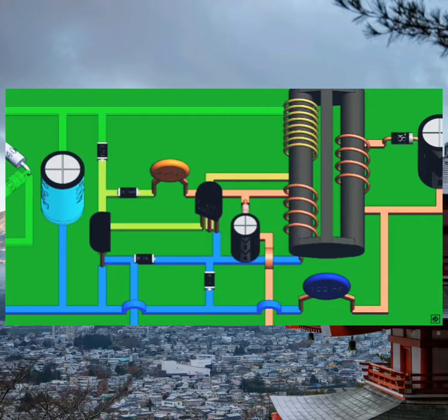Now, this current passes through the 2 megaohm resistor to the base of T1, turning it on. This transistor isn't fully turned on because of the resistance; it turns on partially. Due to the partial turning on of the transistor, a low current passes through the primary winding of the transformer. This induces a low voltage in the auxiliary winding. The induced voltage now charges the capacitor, and then the capacitor fully turns on the transistor.